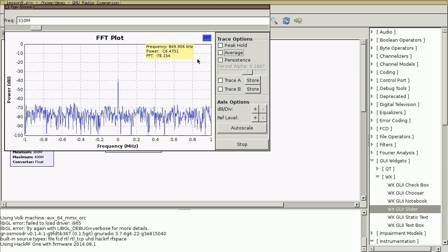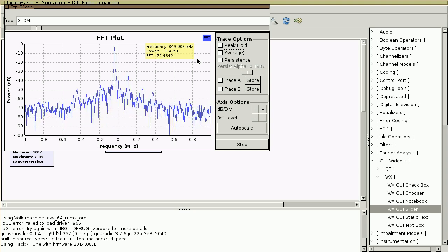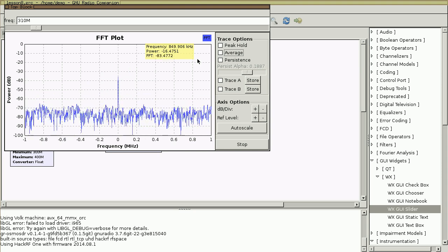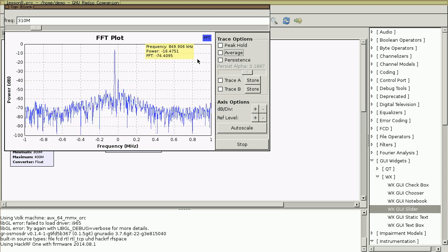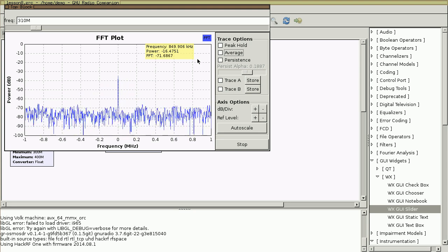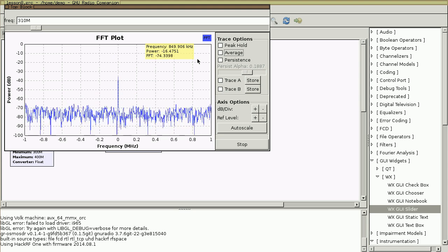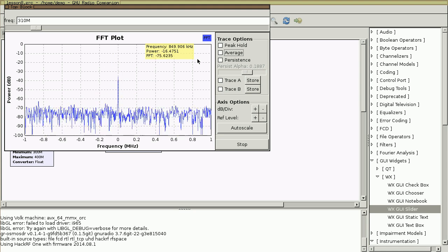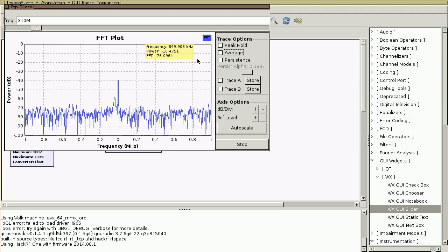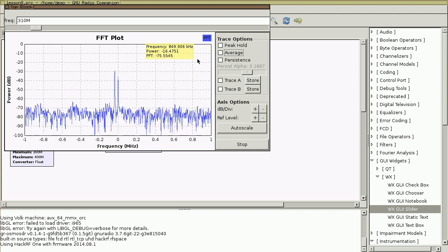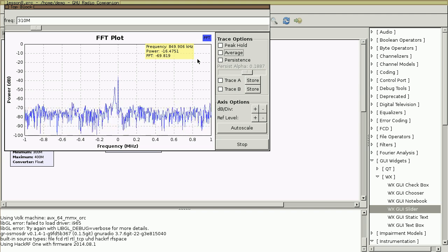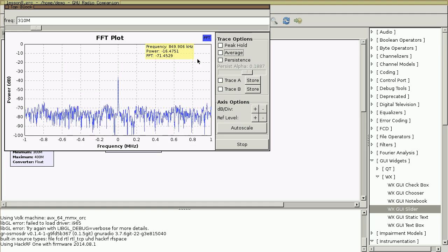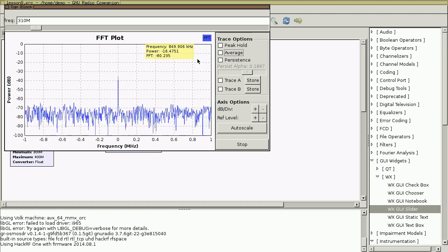If I hold it right next to the antenna of the receiver, you can see we're actually getting some other frequency components because we're distorting a little bit, because we're pretty close to 0 dB. But if I hold it at a more reasonable distance, like a meter away, then I'm at somewhere around -30, -40 dB, and we seem to get a nice clean signal for as long as I hold down the button.